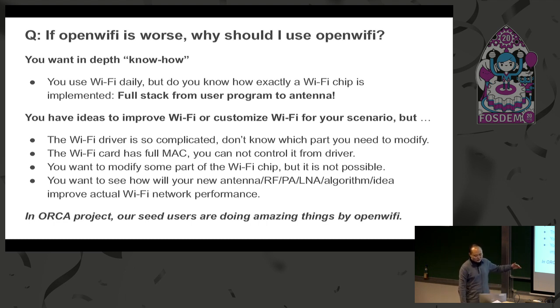So with this design, you have the full stack, right? Open full stack from the user program in Linux to the antenna. I mean, in the FPGA, there's also logic to control the front end and antenna, such as antenna selection, TX gain, RX, AGC stuff. Everything works just like those modules in a commercial chip.